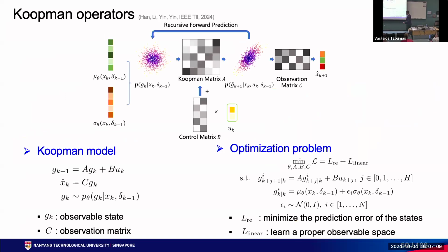There are different versions to update this Koopman model structure. We could put a disturbance term here, but we choose to add stochasticity when we initialize the Koopman model within each prediction step, because our Koopman model does not only predict the next sample instant state. We need to provide good predictability for the entire control horizon.